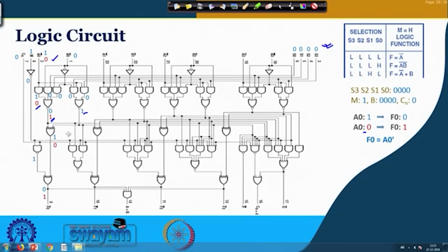So, this is 1 1, which means this is becoming 0, right. So, for this XOR gate, one of the inputs is 0 and the other input is 1 because of m being 1. So, the NAND gate output is 1, okay. So, 1 and 0, then this output is 1, is it fine? So, you can see that this is happening. You can see for other cases also, and it works in that manner.